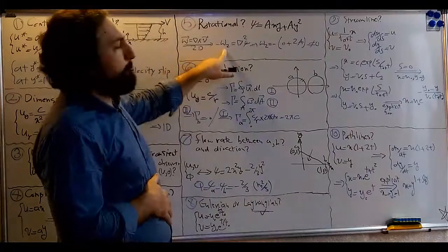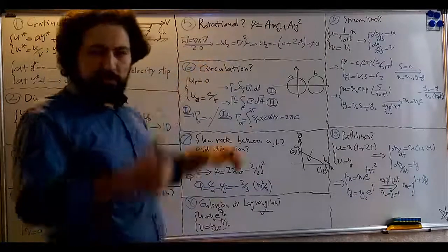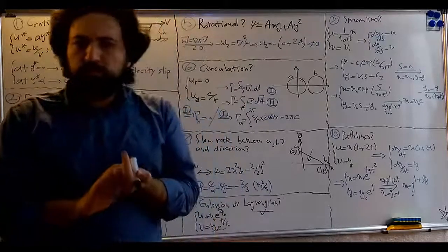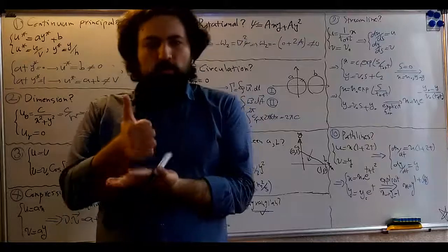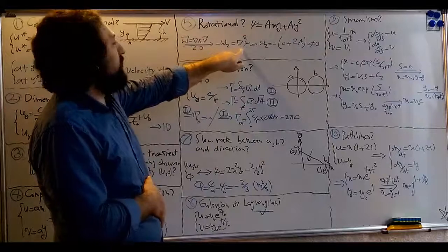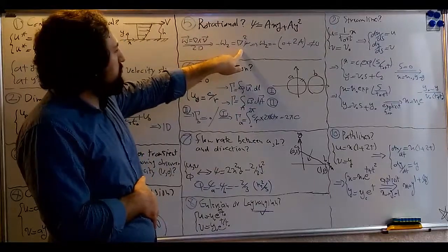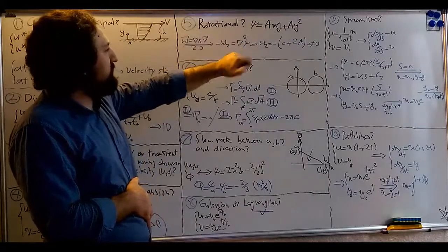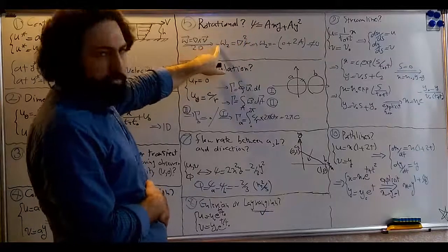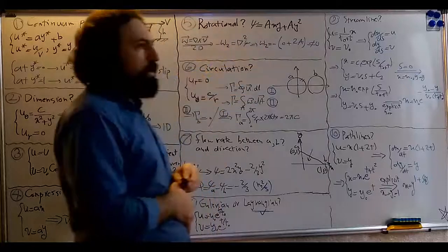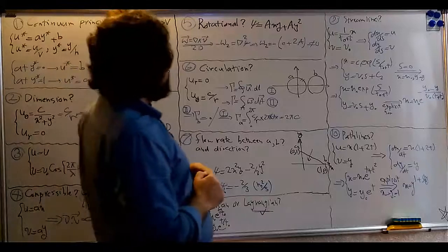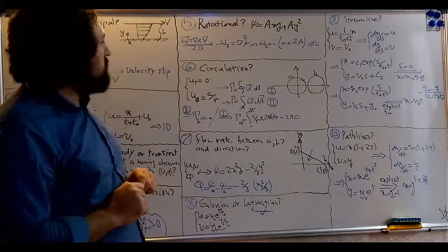The component of the vorticity in z direction, because the fluid is two-dimensional, the vorticity vector just possesses one component in z direction, equals minus the Laplacian of psi. So you just take the Laplacian of both sides of the given relation, and also pay attention to this minus sign here, and the component of the vorticity vector in z direction equals minus twice a, which is not 0.